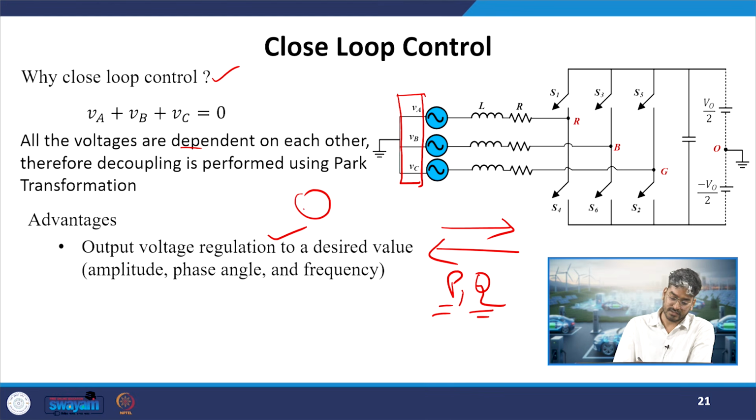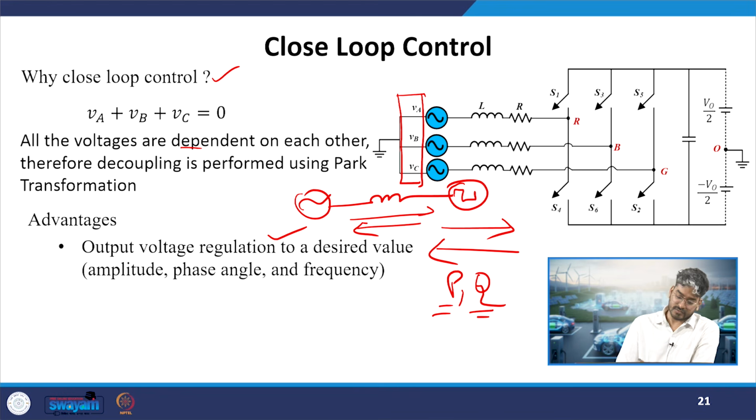So we can consider we have the AC grid on one side and our converter on the other side. Now if I want to control the active power flow, I have to change the angle. Whichever direction of power is required, I will make that lagging or leading with respect to the grid. Okay, so we consider the grid as our reference signal and adjust our output voltage which is generated by our active front end converter. Now reactive power, how will this reactive power be controlled?